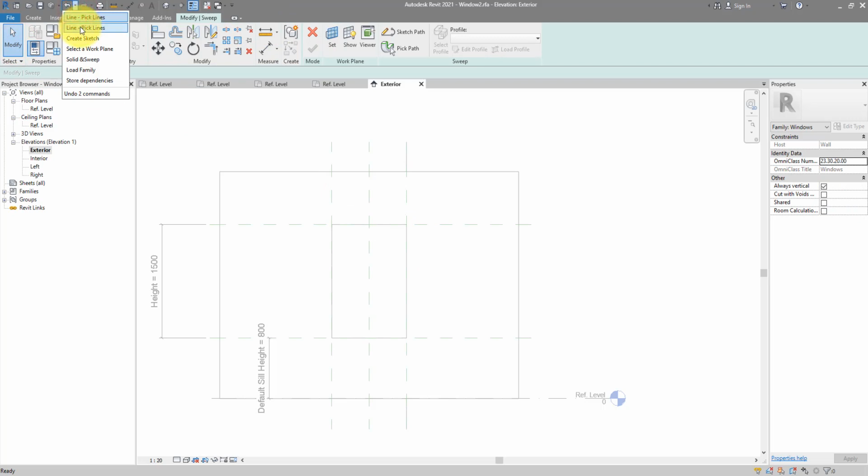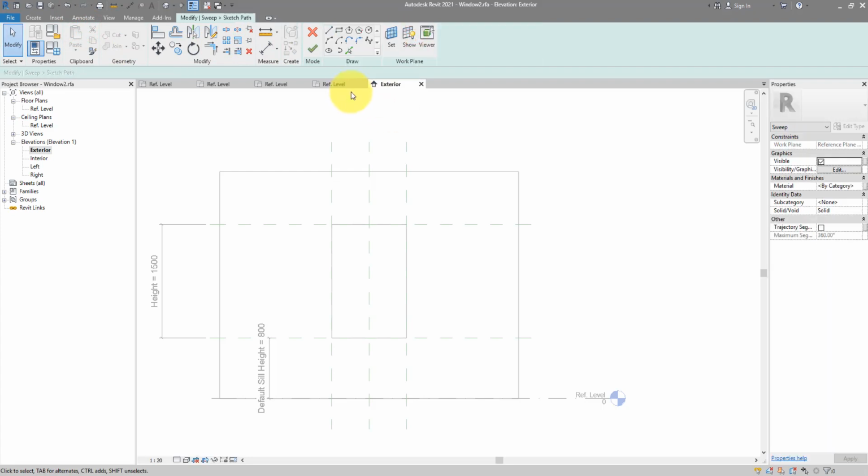You need to undo those two. And make sure to activate sketch path before picking any lines. So once again, pick line, lock on pick, and now they are showing up, just like we expected. We can now trim them to make another closed loop, just like this.